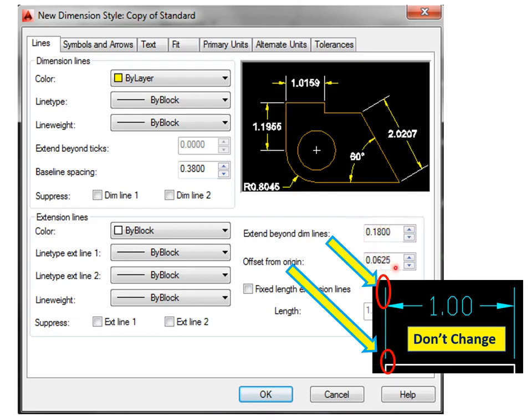The offset, so the gaps between the dimension line and the object line, are 0.0625 inches. I think in the previous chapter I said it was 1/32 of an inch. I need to make a correction. It's 1/16 of an inch, which is equal to 0.0625. So those are the size of the gaps between the extension line and the corner of the object.